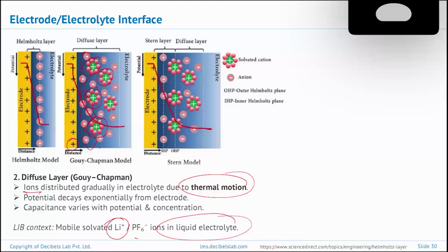So to prevent the lithium ion from coming out once it enters inside the graphite, there is a film that is being created. After constructing the battery, they fill the electrolyte, and then they carefully charge the battery with a slow, low C rate only. They charge and discharge the battery several times, and then slowly the thin film is formed. That is a very important stage called battery conditioning or battery formation. I have discussed that in SEI.